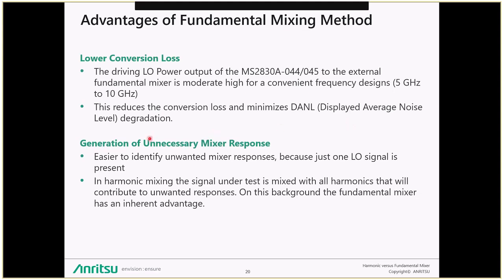Of course, we will also avoid the generation of unnecessary mixer responses. It will be easier to identify unwanted mixer responses because we are only driving one LO signal. In the case of harmonic mixing, the signal under test will be mixed with all harmonics that will contribute to unwanted responses. So on this background, the fundamental mixer has an inherent advantage.